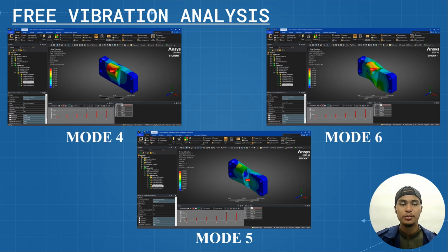And these are modes 4, 5 and 6, which are rotational modes, or twisting movements, from the free vibration analysis. Mode 4 is an X rotation. It is twisting like a wing rolling. Mode 5 is a Y rotation. It is nodding like a car tilting forward. And lastly, mode 6 is a Z rotation. It is yawing like a steering turn.